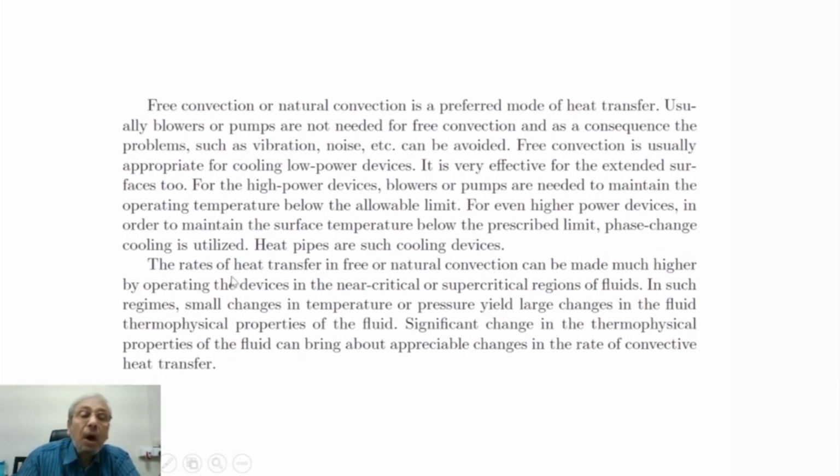The rates of heat transfer in free or natural convection can be made much higher by operating the devices in the near critical or supercritical regions of fluids. In such regimes, small changes in temperature or pressure yield large changes in the fluid thermophysical properties.